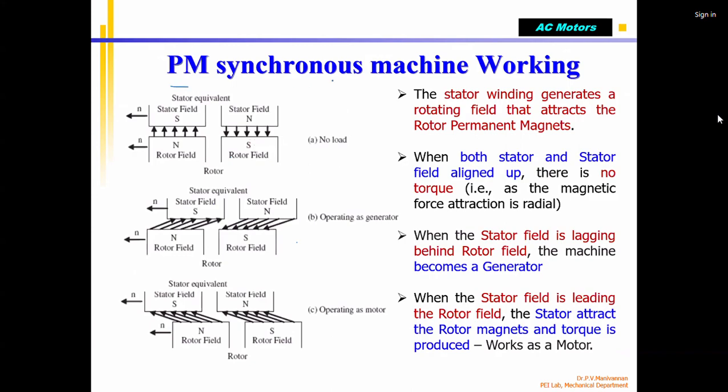We know the permanent magnet synchronous motor can also work as a generator. Correct? So, for example, in no load condition, the stator magnetic field is rotating with NS. Correct? My rotor, there's no load, no friction. I think theoretically the rotor has zero mass. Correct? Mass of the rotor is zero. That means it is able to run with no friction, no inertia, this is J, correct? Inertial load. So that means it is able to catch up, NR equal to NS. That is no load condition.